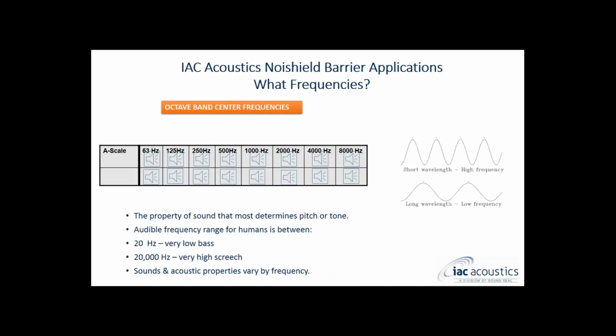Another key parameter when you're looking at the performance of barriers and designs for barrier components is frequency. Usually the noise that you're trying to attenuate with a screen exists at lots of different frequencies, high frequencies and low frequencies. And that means that the noise is going to have a combination of short wavelengths and long wavelengths. This is important because not only do people hear differently at different frequencies, but materials behave differently at different frequencies. Something that's a very good barrier to sound at a higher frequency may not be such a good barrier to sound at a lower frequency.